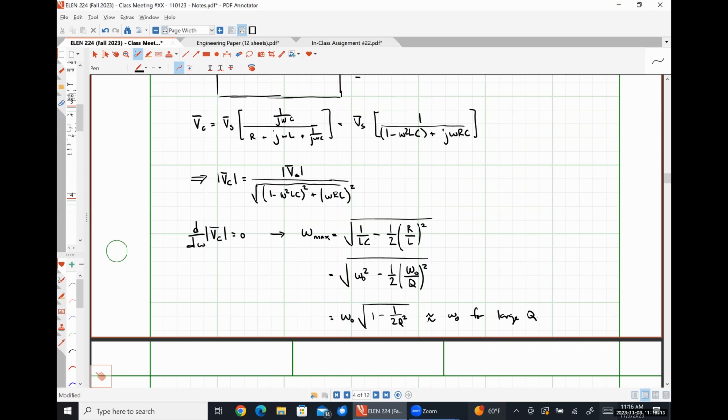For our particular example, plugging in the Q factor of 60, we would actually see that the maximum voltage drop across our capacitor is like 601.25 volts, right? So it's a very, very small increase over the exact value that we got when we excited the circuit at our resonant frequency. Okay. So what does this tell us conceptually?